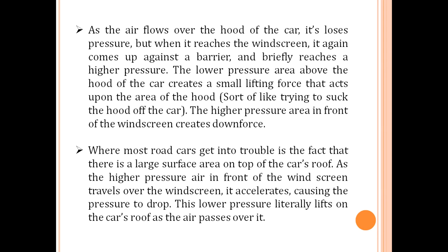So when these air molecules collide with the front windscreen of the vehicle, the pressure will be increased there and the velocity of the air molecules will be decreased there. As the pressure of the air molecules is increased, this high pressure will act as a downforce onto the front of the windscreen of the vehicle body.